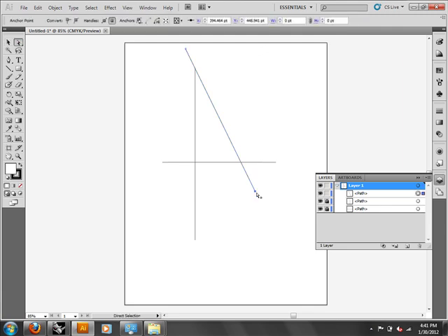is you can pick the anchor point on the end of it, and because of the way that smart snaps work in Illustrator, you can grab that point and snap it to the ghost intersection of those 2 pieces, and so you actually don't even have to trim it. It's actually a quick operation. But be careful when you have more than one line, because it can snap everything to something else. Yeah, just like AutoCAD. Exactly. But I like that.